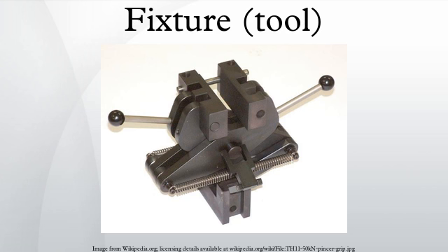Support: in designing the locating parts of a fixture, only the direction of forces applied by the operation are considered, and not their magnitude. Locating parts technically support the workpiece, but do not take into account the strength of forces applied by the process and so are usually inadequate to actually secure the workpiece during operation. For this purpose, support components are used.